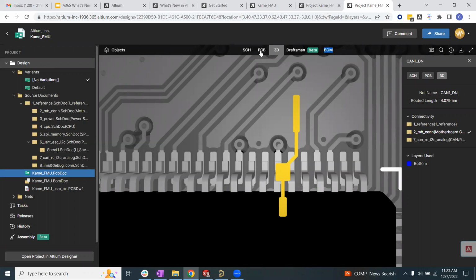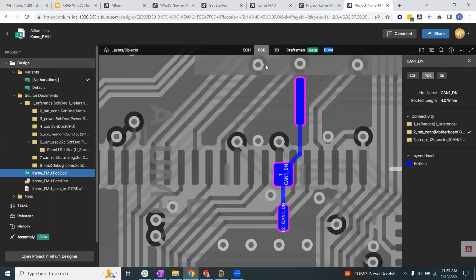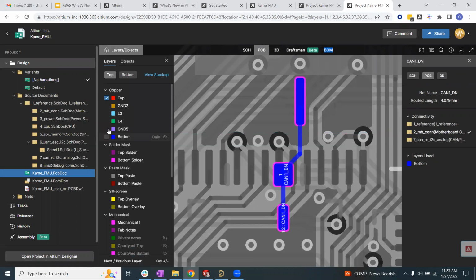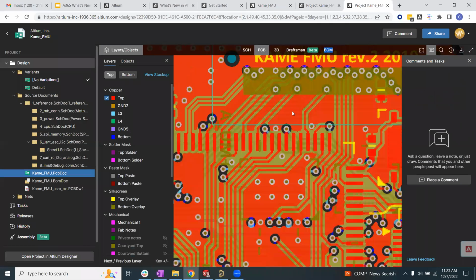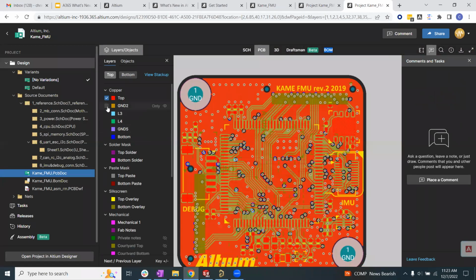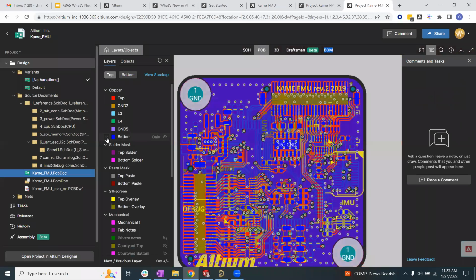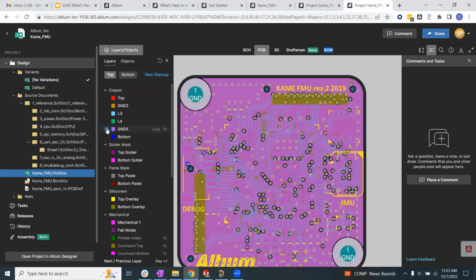And if you're in that 3D view or in the PCB view, you can use the tabs up above or the ones that are here, but you can see also the layers. Now, if we just click in here, and I'll clear that filter by clicking out of this item, you can see here, if these are turned on, it will display that as the top layer now. So before we were only able to turn layers on and off, but now we can select any given layer that's turned on to view, and it will become the forefront of what is visual here within the screen.